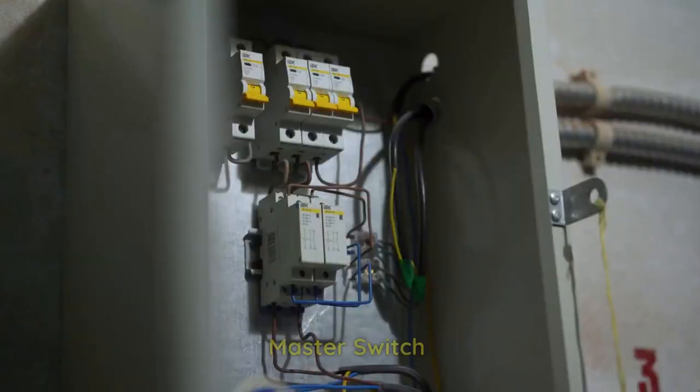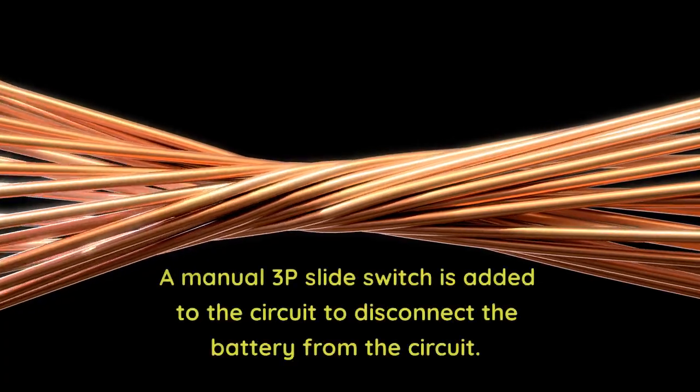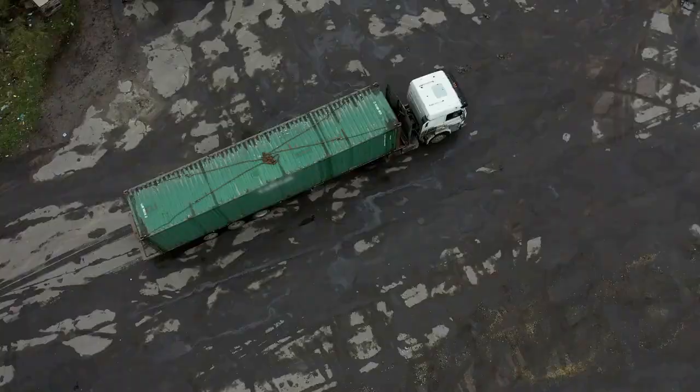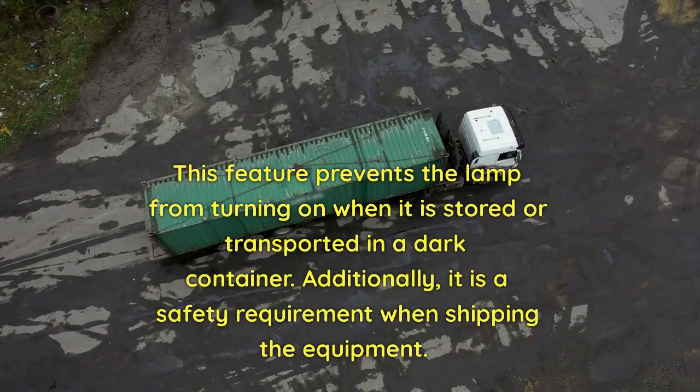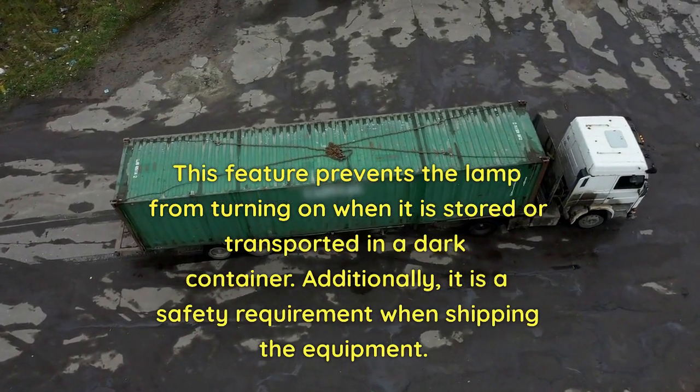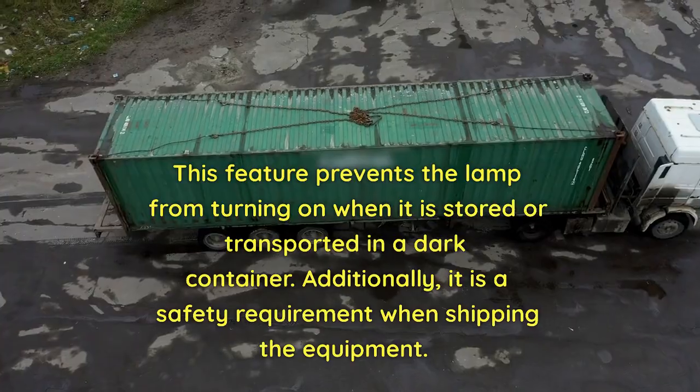Master switch. A manual 3P slide switch is added to the circuit to disconnect the battery from the circuit. This feature prevents the lamp from turning on when it is stored or transported in a dark container. Additionally, it is a safety requirement when shipping the equipment.